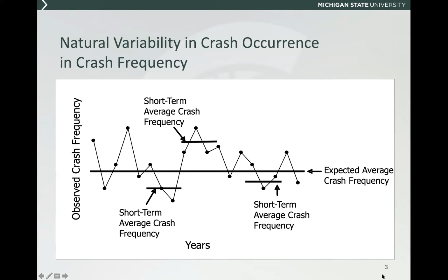Okay. And so we talked about this a little bit last time, but when we're relying on short-term crash counts in order to determine when and where treatments are appropriate for implementation at a given site, there's some uncertainty involved in that process, just given the natural fluctuation in crash data. For example, if we examine data over any individual period, or say a 2-year or 3-year average, we can see significant variability as compared to the long-term average, and that could be due to factors that are completely unrelated to the actual safety of that site in consideration of site-specific factors. And so in many instances, we just have limited crash data, which potentially complicates our analyses. And so that's what we're going to talk about addressing here.